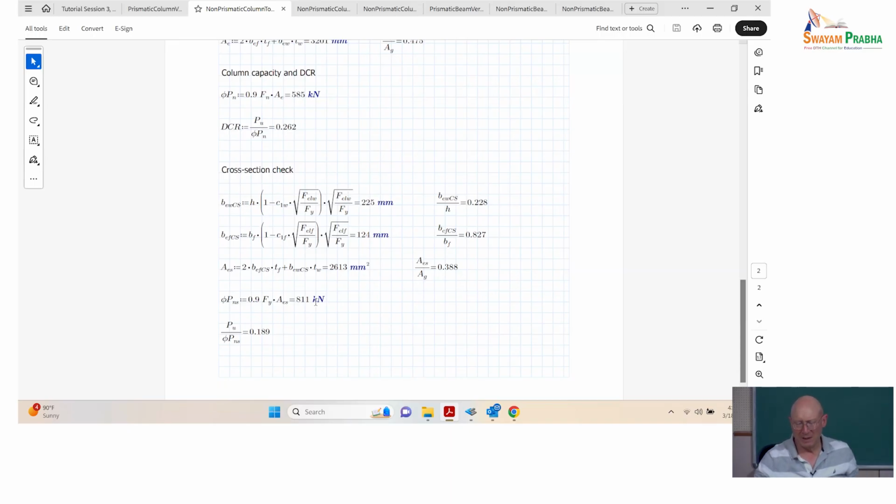Okay. And that check would actually send us to the bottom of the column, which is what you might expect on most tapered columns like this. If it didn't have crazy effective width reduction, you'd say, I've got the smallest cross section at the bottom, so I would think that's where I'm getting the largest cross section utilization, or the demand to capacity ratio, right?